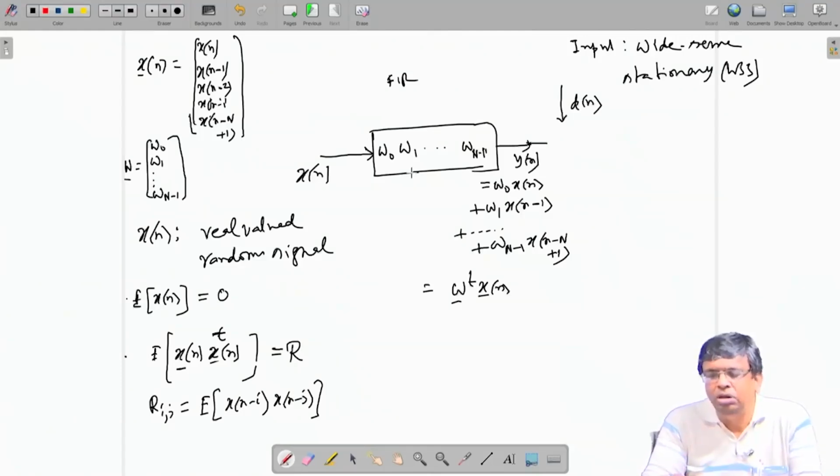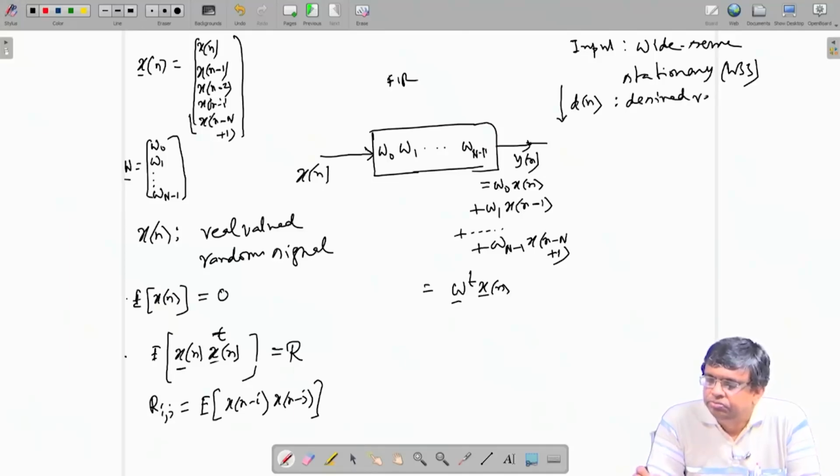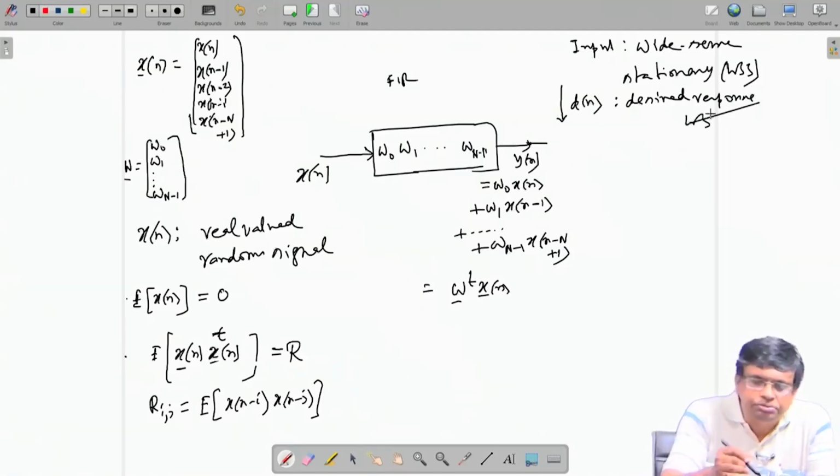That time d n will be given, and then d n is not given afterwards. Whatever filter you designed, be happy with that and use it for a while. Again a training period will come, and like that. So, d n is called the desired response, is also a random signal. This is also WSS, sorry.